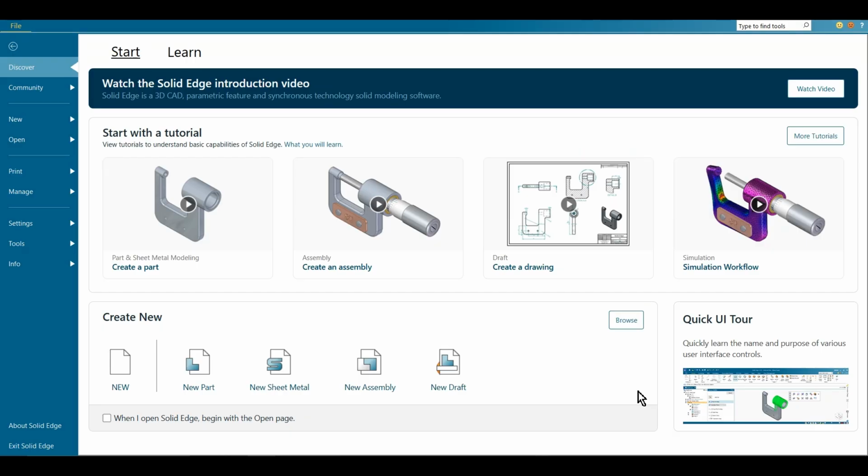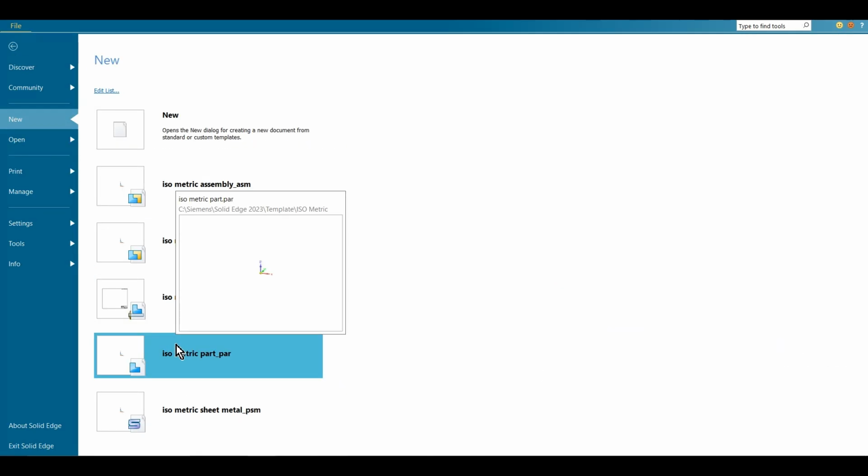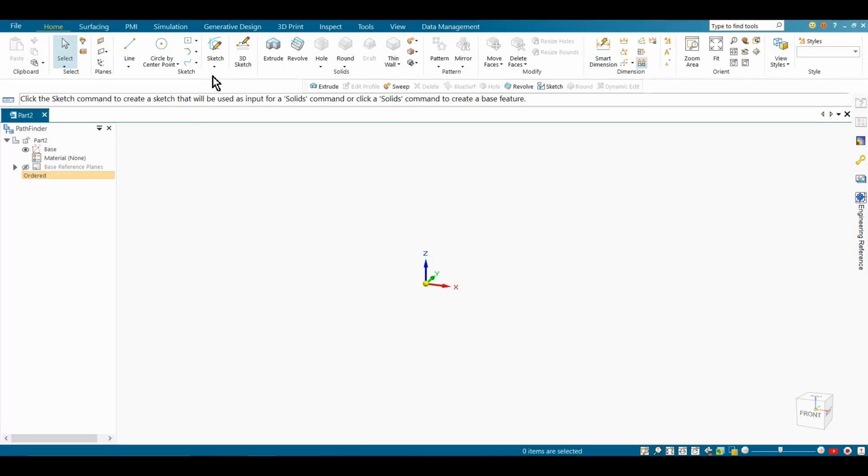In the next part of our SolidEdge learning series, today we will see the SolidEdge sketching environment. For that, I will go to the SolidEdge isometric part environment. Here, there are some sketching tools, but to access them, first we need to go into the sketch mode.